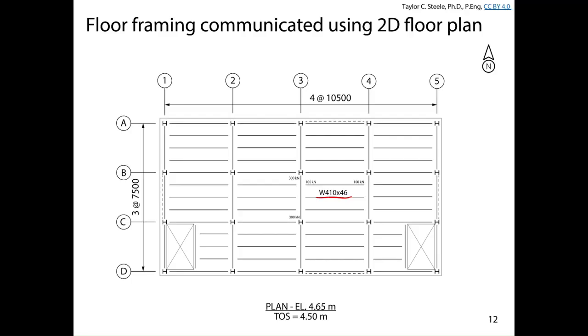I just made it minimalistic here to not overwhelm everybody the first time I showed you a floor plan. But I also want to see some connection details here. I want to see where the columns are, some column lines, some base spacings. And if you have things like steel, it's nice to denote that, the W sections, you want to say they're to grade, whatever, ASTM A992, grade 50, etc.